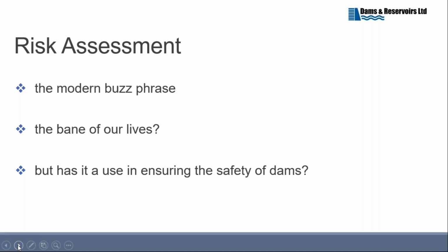And then, from my point of view, a very interesting phase that we've moved into is where we've used it for asset management. Now, some of you will have heard and been involved with PRA, probabilistic risk assessment, where when you're faced with a situation where you've got 80, 90, 100, 200, 300 dams in your portfolio, where do you spend your money first? Which one is the most important?